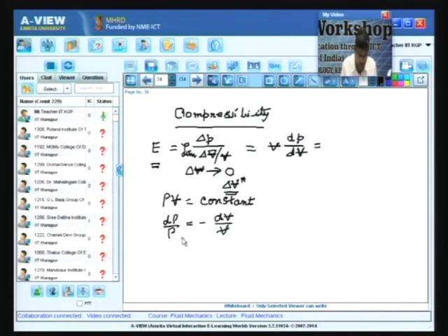So, we see that we can define this bulk modulus of elasticity in terms of rho. Now, here there is one thing I forgot to tell you, that as I told at the beginning, you must remember that for all substances pressure and volume bear an inverse relation. So, if we take delta P in its positive sense as an increase in pressure, then delta V will be a decrease, a negative. So, to define a scalar property like E, we have to incorporate a minus sign.